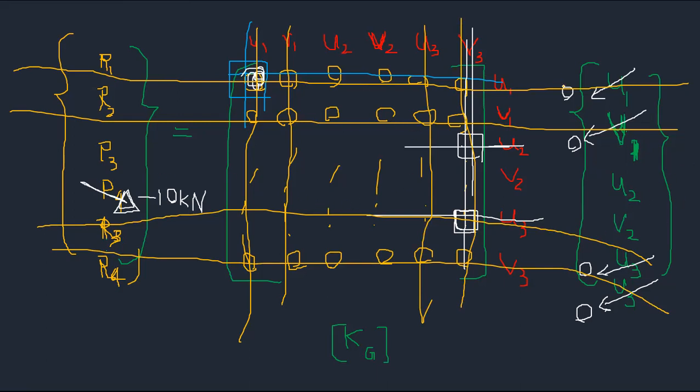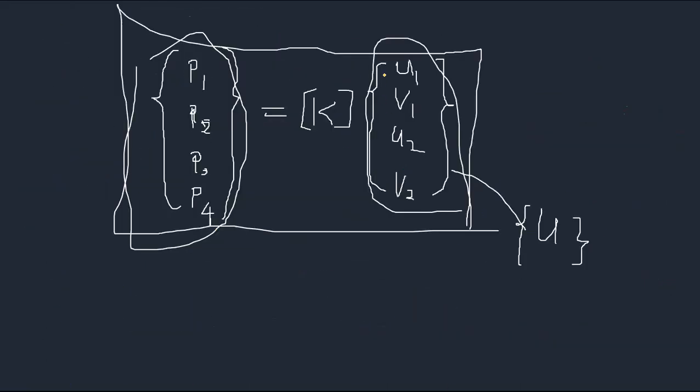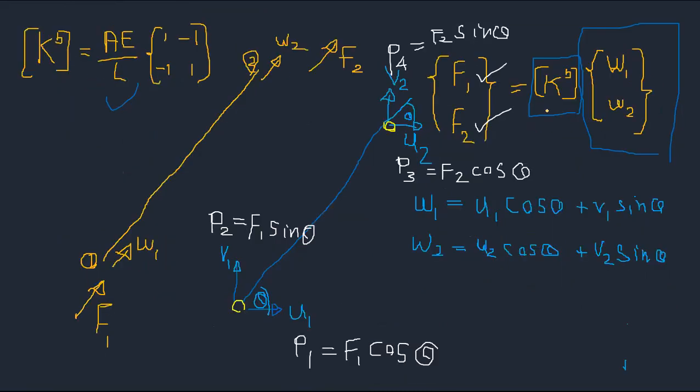Then we plug the displacements back and find the forces. These are the FEM outputs. Because we know the displacements, we can plug them back and find the displacement along the longitudinal axis. Once you do that, you can find the member force, tension or compression.